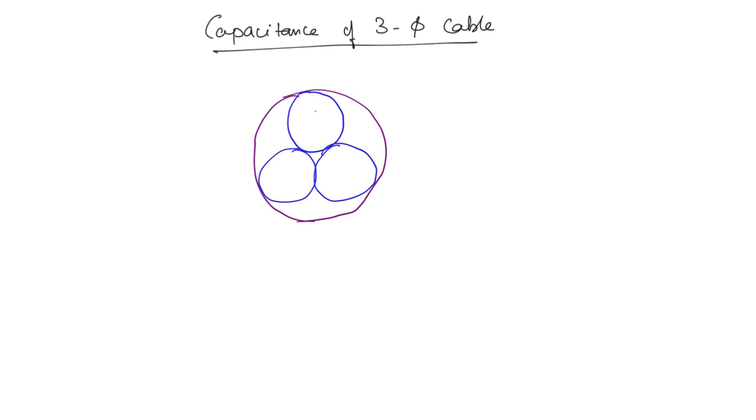So inside this you can take the core. This is the core. Okay, so this entire region is the insulator for each of the conductors. Now what is going to happen? There is an insulator here, there is a conducting surface. So it is a capacitor, right?